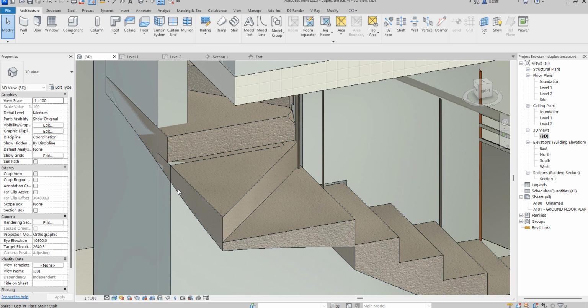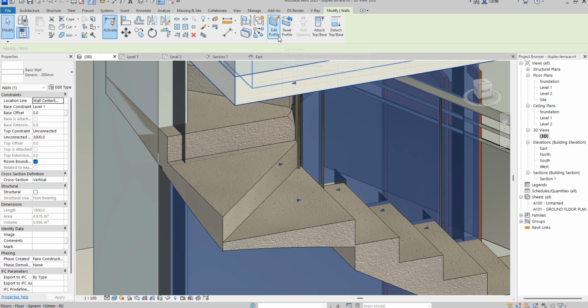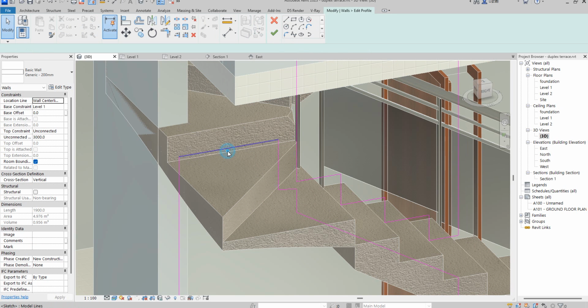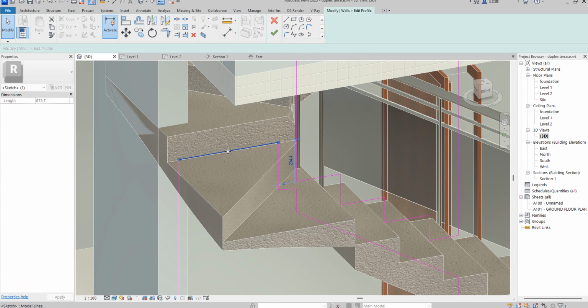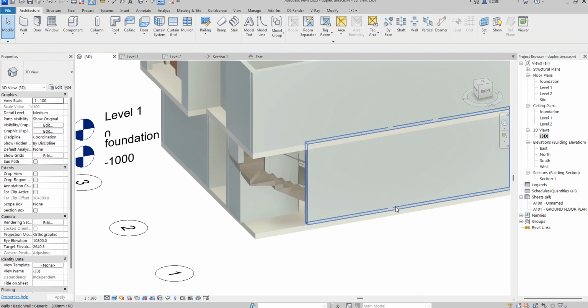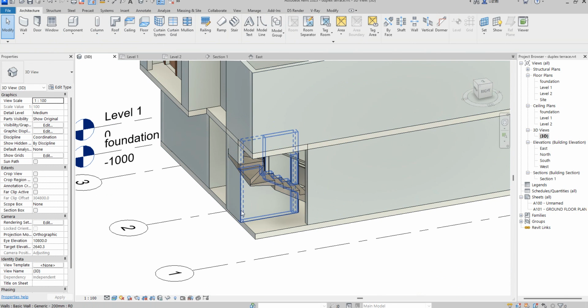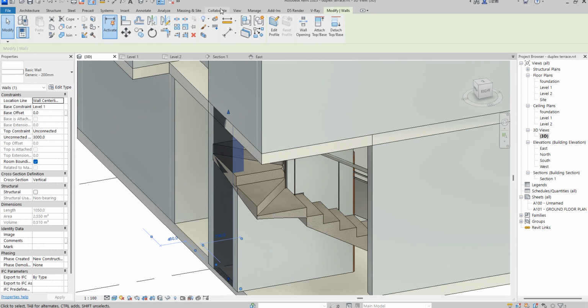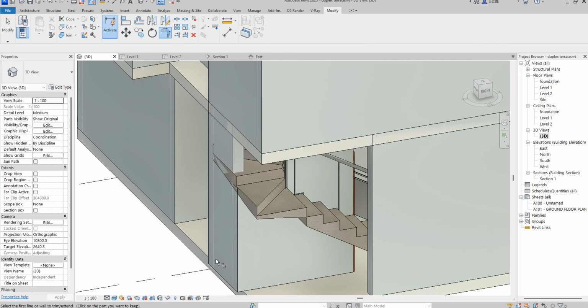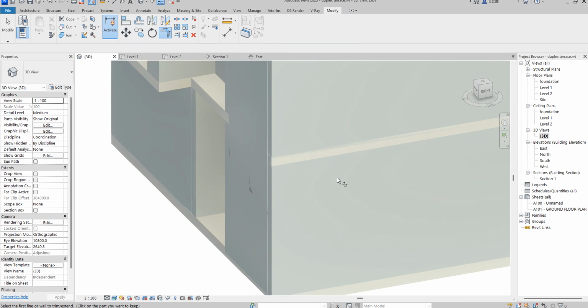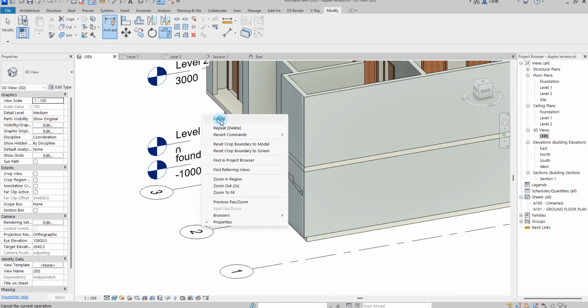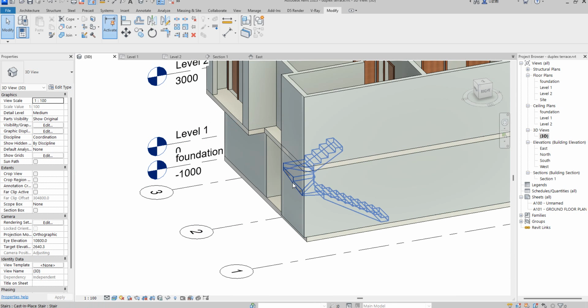So it's not going to be seen from this stair. I will just do that by selecting, and I will strike the down arrow. We are done with this. Now as we are done with this one, we just need to close this up. Click and say close, then you close this shut. So it's finished. Now you need to edit the staircase so that it's not going to be seen.